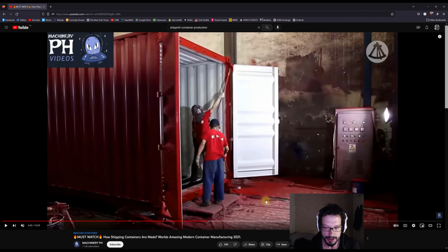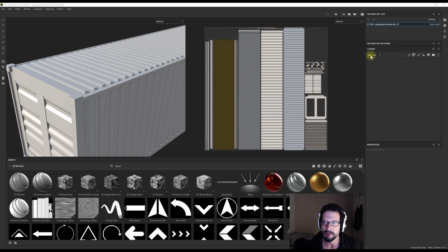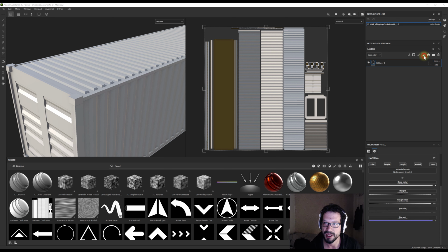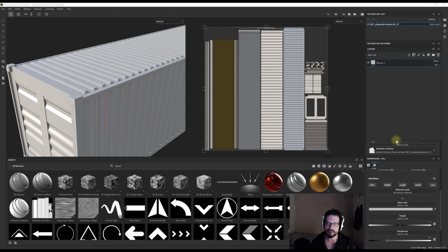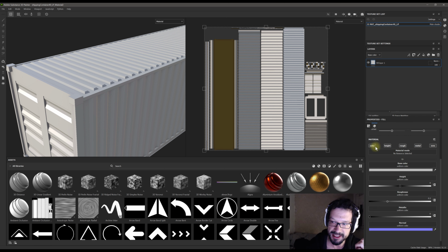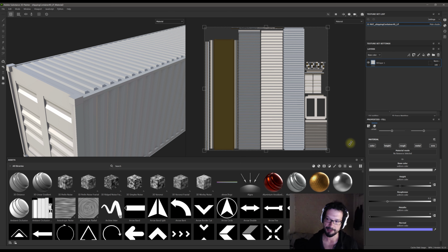Okay? So let's get into Substance 3D Painter and start with our first layer. Right now my layer stack is empty, so I'm going to click here, which is add fill layer, and I'm going to add a fill layer. Now, all layers, including masks in Substance 3D Painter, come with these settings. So since we have selected PBR Roughness Metallic as our project, as you can remember from the project configuration, it doesn't allow us to change it right now because you have to set it up from scratch, but we have selected PBR Roughness Metallic.